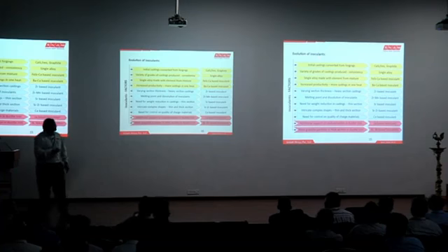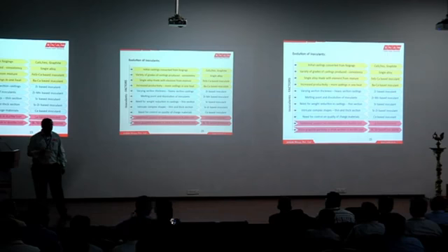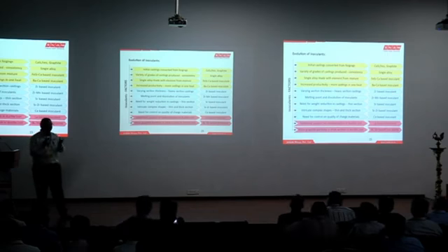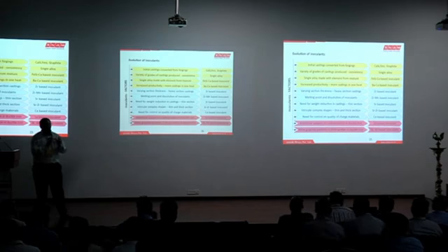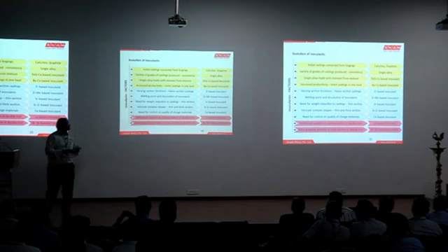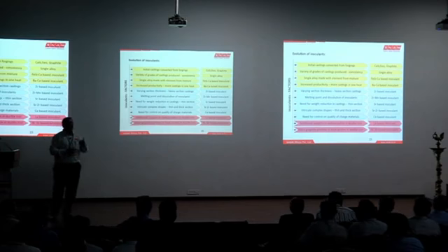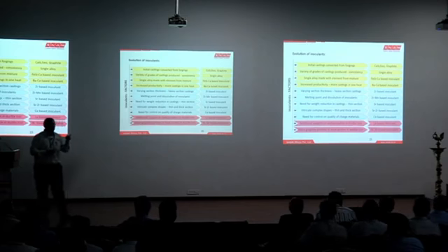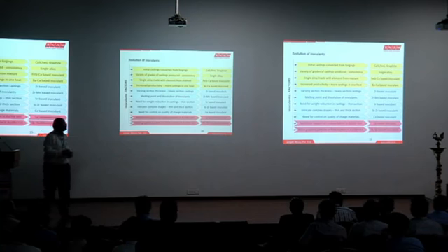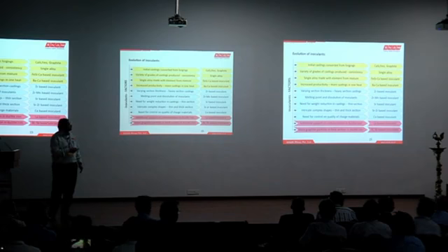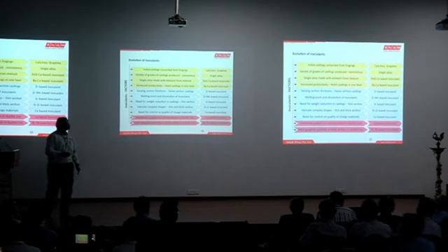Just made a synopsis. Initially, castings got converted from forgings, from components which were forged. When we tried to match the same elongation and same yield strength, but compromising something on the strength, people started converting forgings into castings. That is how some of the steel grades can be directly replaced by a cast ductile iron material.